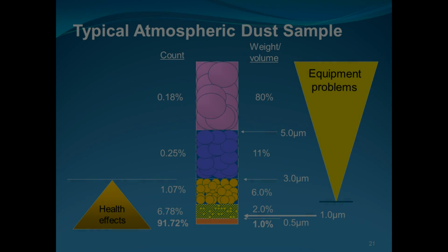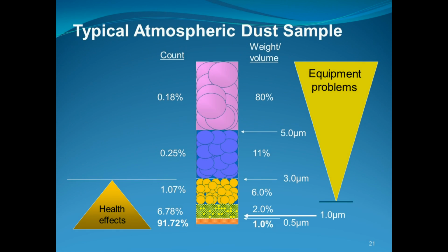And again, filters just don't have the capability of capturing those things. If you look at the math, if 98% of the particles are below 1 micron in size, and no filters can capture particles below 1 micron, well, even the best filters on the market today, those 5-inch pleats and the 3M Filtrete, they're only capturing 2% of the particles that we have in the air. They're missing the other 98%. Well, that doesn't make them a bad filter. No. It just doesn't make them an air cleaner.